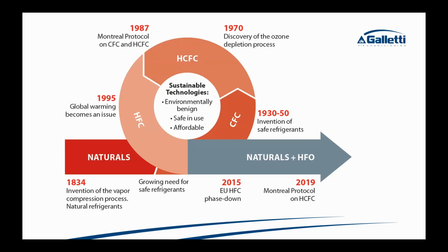So if that's approved, then it'll go to UL. UL will then have to do their own studies, and then from there likely the EPA. I think things are going to be a quick flip at the EPA, the reason being the GWP of R290, I believe, is 3. And a big indicator that flagged a lot of this to my attention last year, and made me think this is definitely going to be the case sooner than we think, was when the DOE actually funded Copeland $2.5 million towards R290 compressor development for heat pumps.